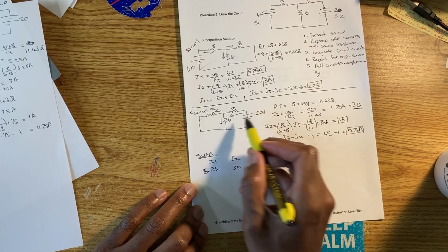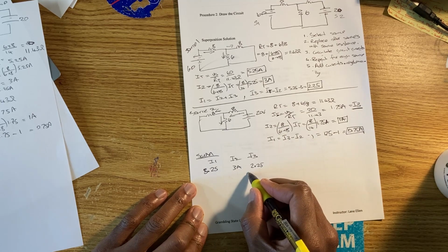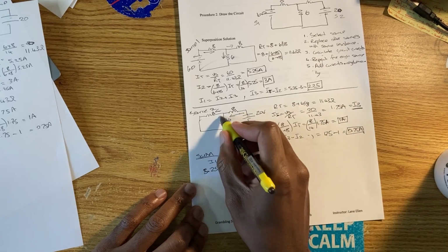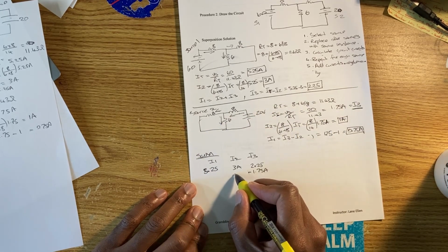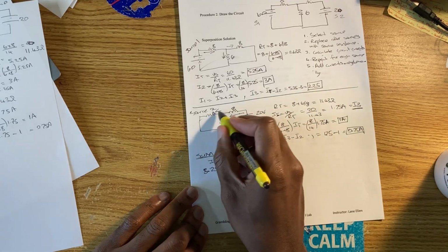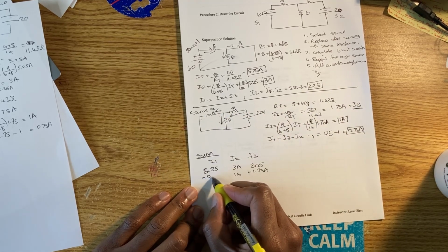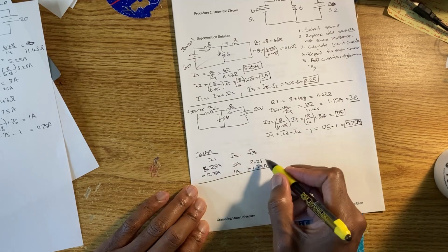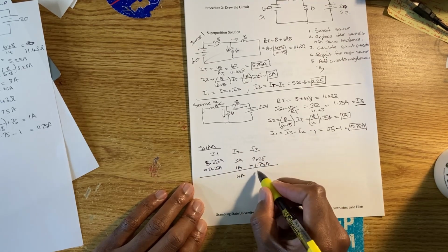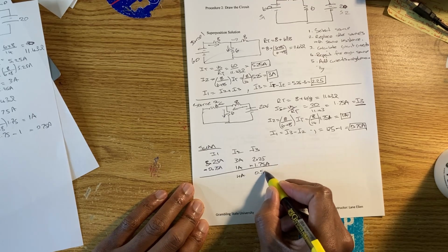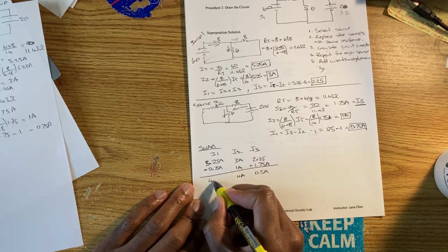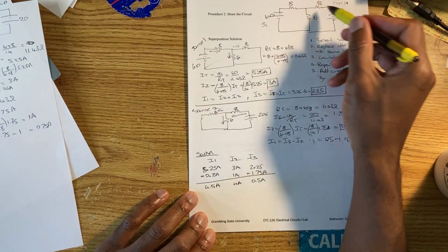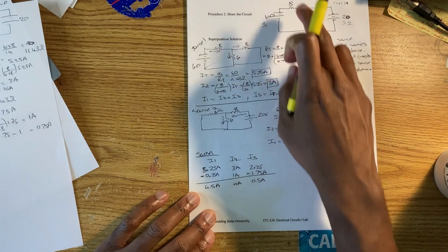So again, if you look at I3 here, the current is different. So for I3, we have minus 1.75 amperes. What about I2? The current is the same, so it's positive, so we're going to have 1 ampere. What about this one? The current is opposite, so we're going to have minus 0.75 amperes. And so of course now we add them together. So we get 4 amperes here, we get 0.5 amperes here, and we have 4.5 amperes here. So this is the current that is actually flowing in the circuit with the two sources. Now this is the current you use to calculate the voltage drop here.